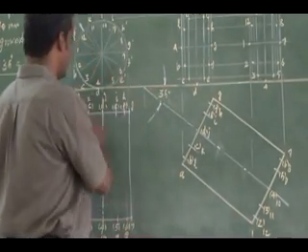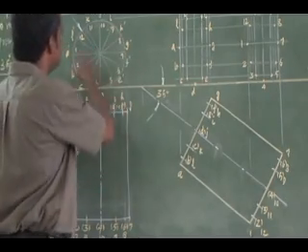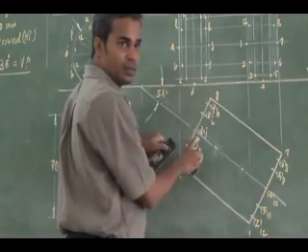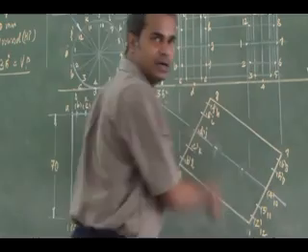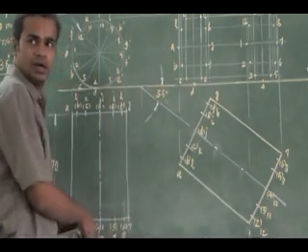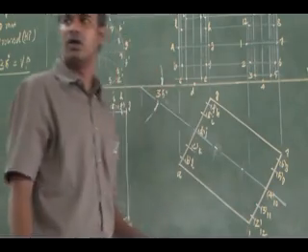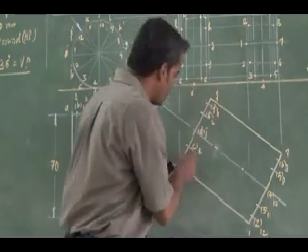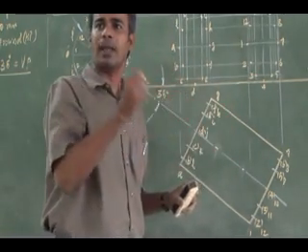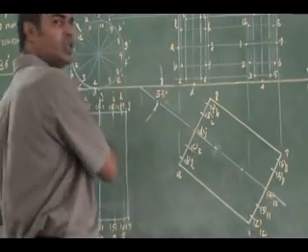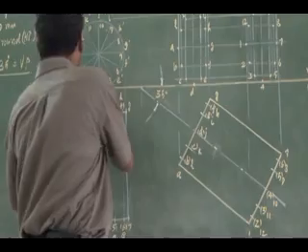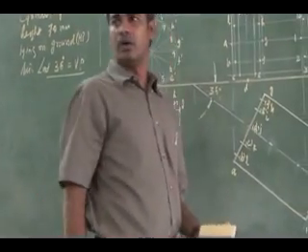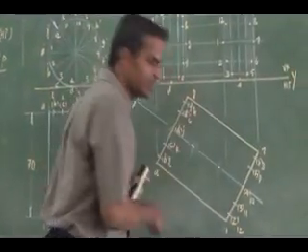Then I can measure the base, which is 50 mm, so 25 mm perpendicularly on each side, and finish off the rectangle in an inclined manner. The same rectangle is drawn to show the final top view. In this final top view, you have to carefully mark all the base circumference points, similar to the previous top view. Measure those locations carefully, mark them in the final top view, and give the notations carefully.